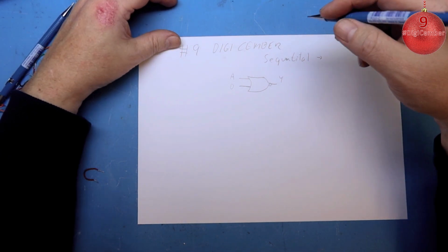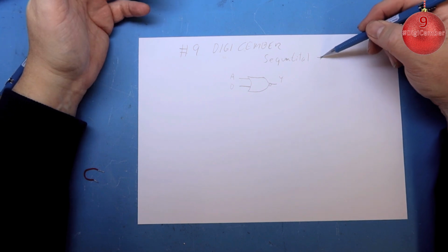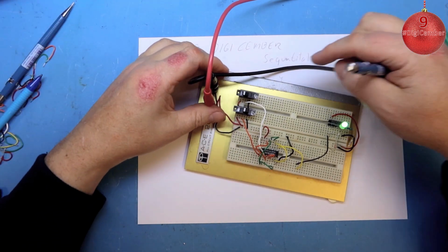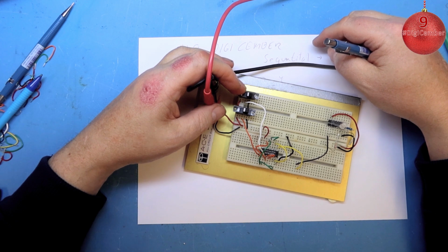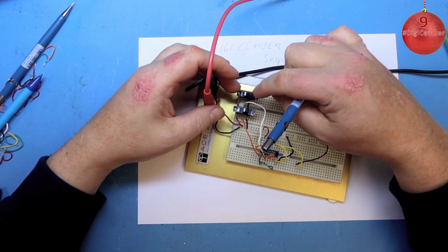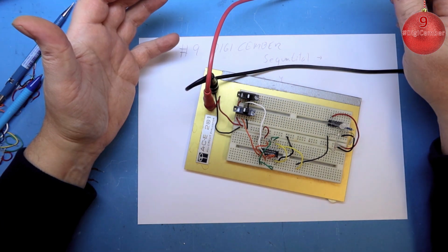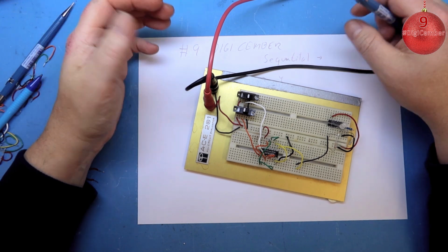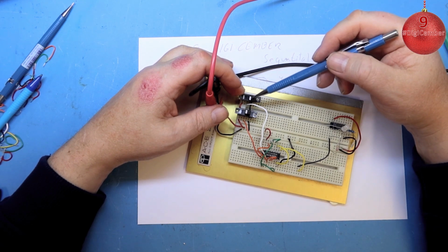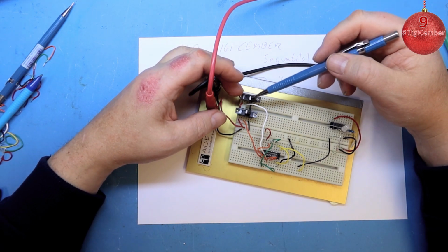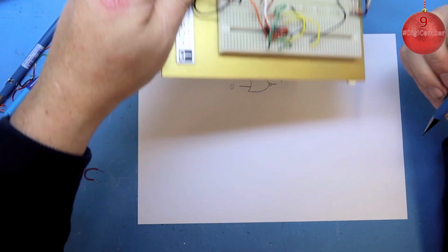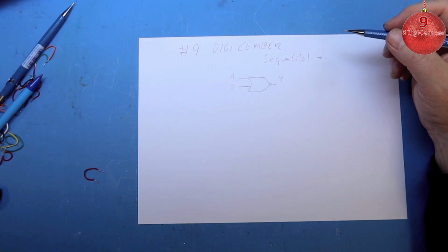This is logic that happens in a sequence, or actually can store something and keep the result afterwards. That means it's acting as a switch. If I have this switch here on my breadboard, and I move it like so, it's keeping its value. It's not springing back to the original position. If it had been springing back, it wouldn't store the result. So when I move this switch from 1 to 0, I actually store the result in the switch. So this is sequential logic. Because of the force I put on this, it will keep its state. And that is sort of what we are going into today.